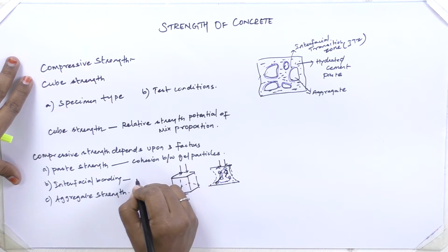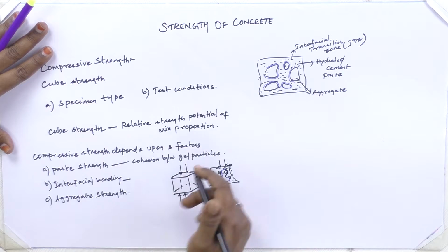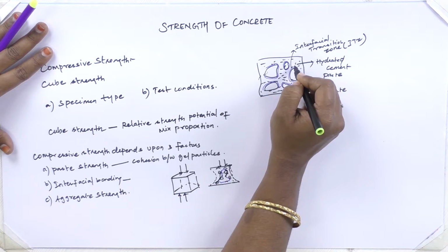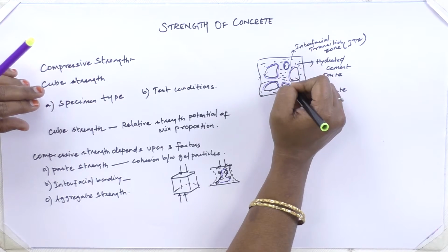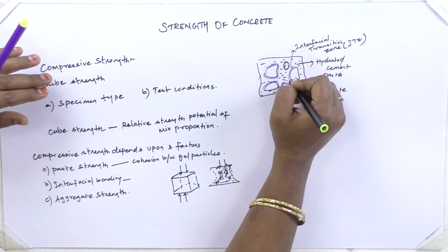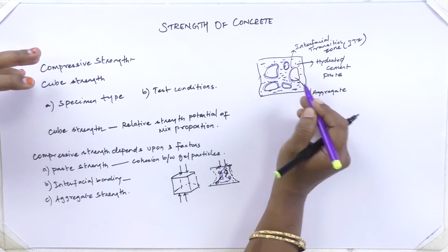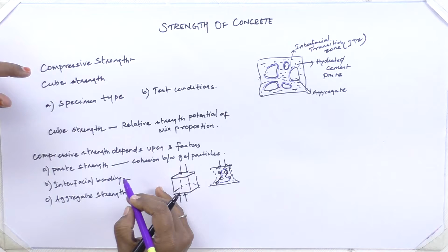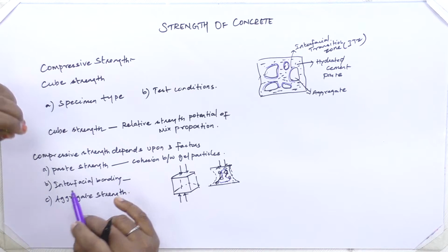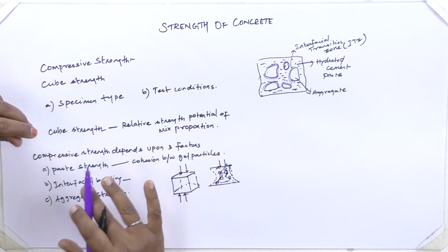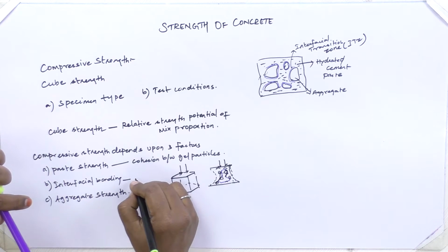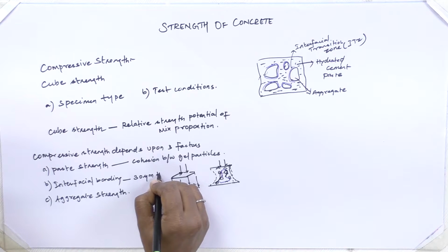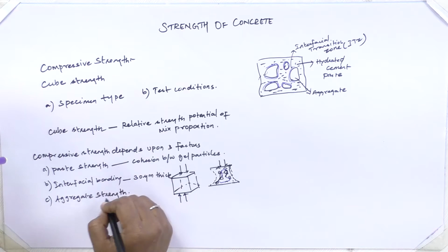This interfacial bonding is nothing but the boundary present between the paste and the aggregate, and this ITZ has a different property than that of the cement paste and the aggregate. When this interfacial bonding ruptures, it leads to failure. It is about 30 micrometer thick.